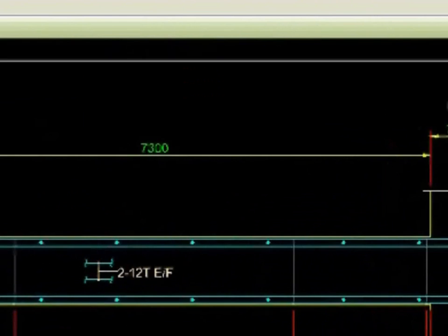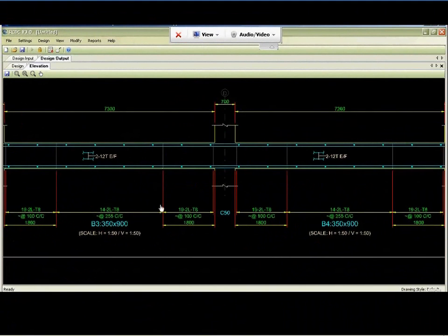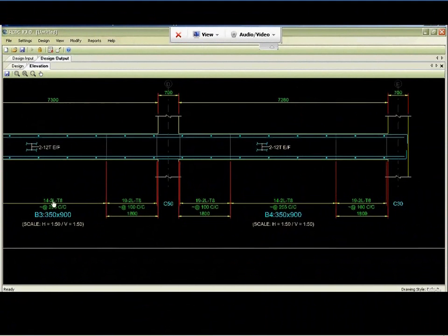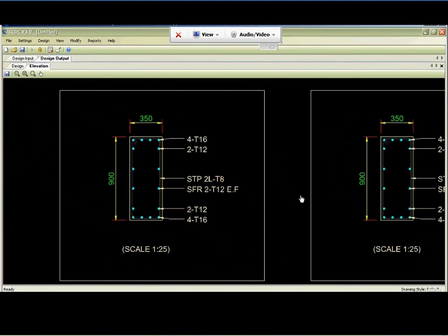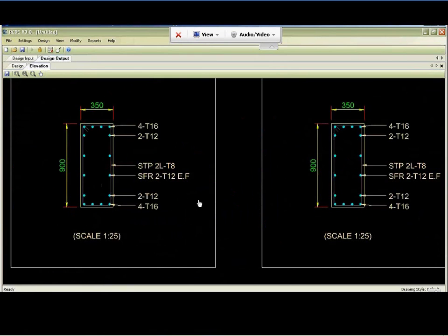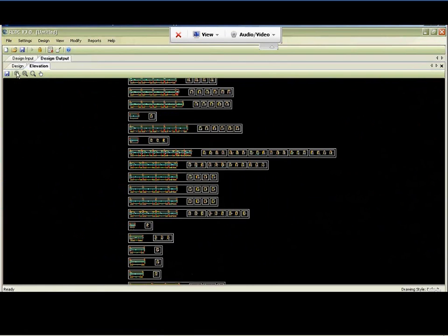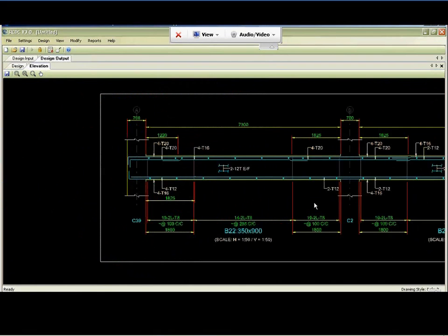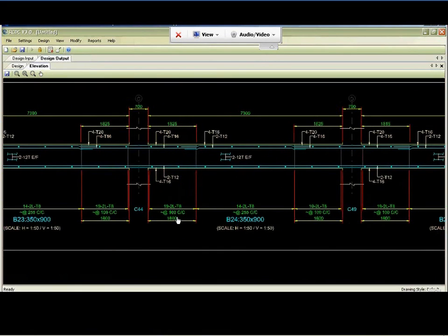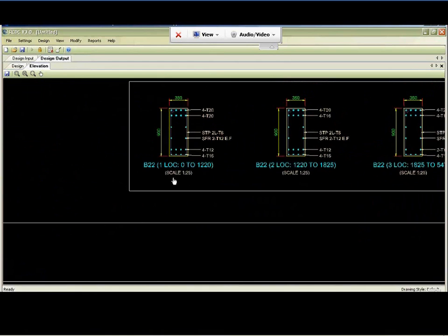We can just zoom this with everything: spacer bars, the bends shown to scale, shear reinforcement, indicative grid lines, everything. And we can also zoom to show the cross section, so stirrups, face reinforcement, everything. In case you're using 4 or 6 legged stirrups, it will give you those. Or this is perhaps a different beam where you can find sections are changing, and since sections are changing, there will be multiple cross sections if you pan to the right end.